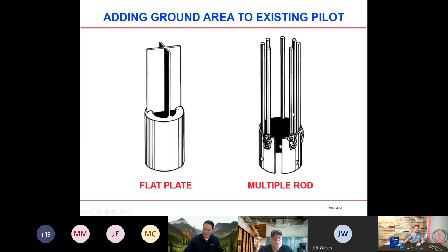I've been on applications where we had a pretty poor flame strength, and one of our service people we were working with had some welding rods that he went out into his truck, brought in, bent up and put inside of that nozzle. And each time he added one of those rods into the nozzle, you could really see the increase in flame strength going back to the flame relay. So it does work. I've seen it firsthand.